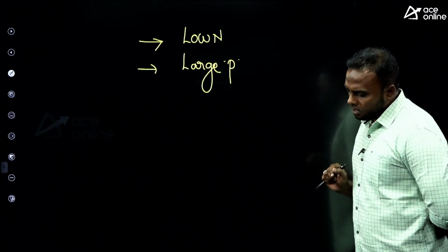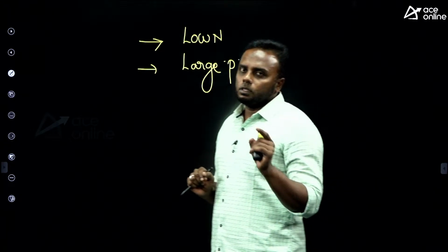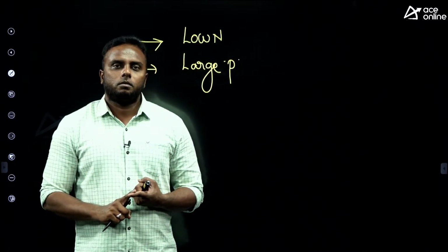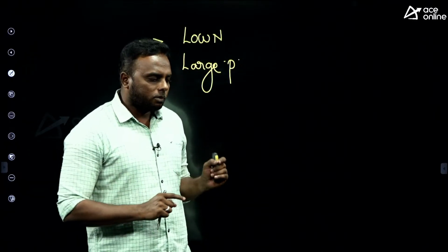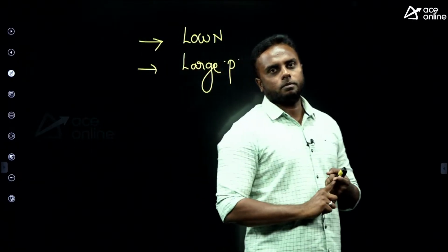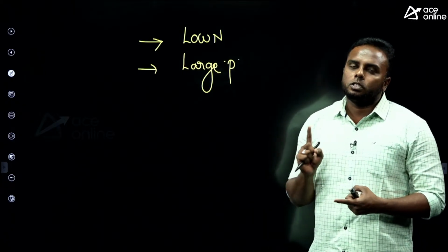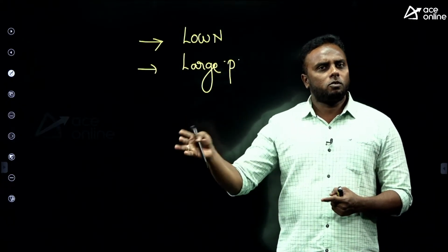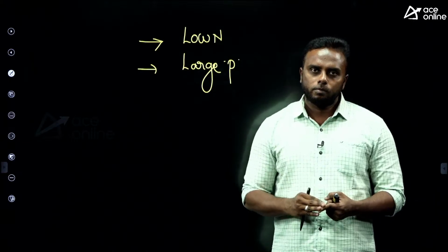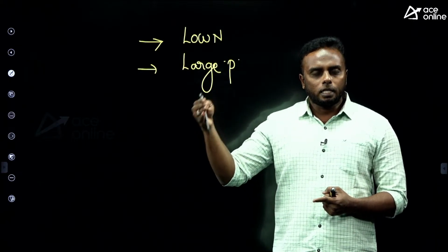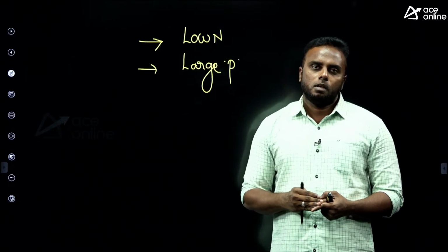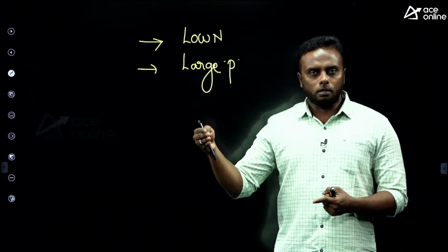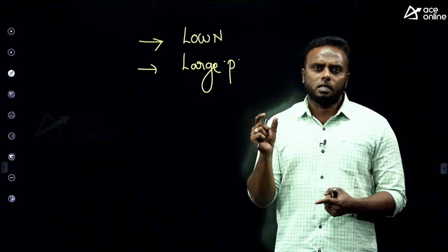The reason is that induction motor speed is almost constant. If you consider the 4-pole case, the synchronous speed is 1500 RPM. The no load speed of the induction motor will be very near to synchronous speed, say 1490. Whenever the load on the motor increases, the speed drops slightly, some 30-40 RPM.